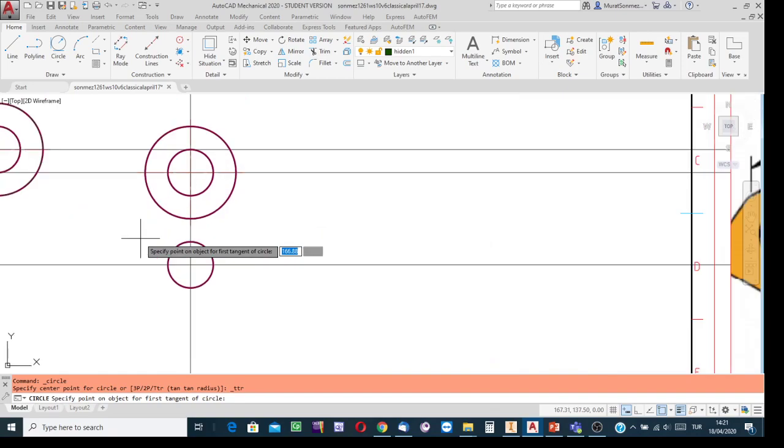So at the indication stage it is important which quadrant of the available circle you expect the tangent point in, and then show the circle at that quadrant. Move the cursor to the vicinity of the third quadrant, because the tangent point is expected over there.